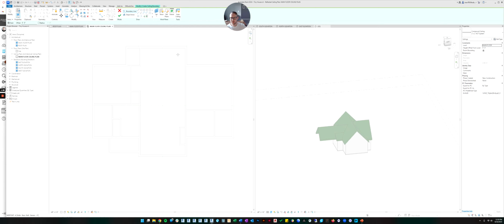We're not going to do a vault in the main room. Probably if you were designing your own house, I would put a vault down the middle. In that case, you'd have to draw 2 ceilings and you'd have to slope each ceiling. We're not going to do that in this class. So I'm just going to draw 1 ceiling that goes to the inside face of all of the walls. Even on the porch, I guess. Well, technically the porch would have a different ceiling than the rest of the house. It would have soffit probably in there. So we'll exclude that for now.